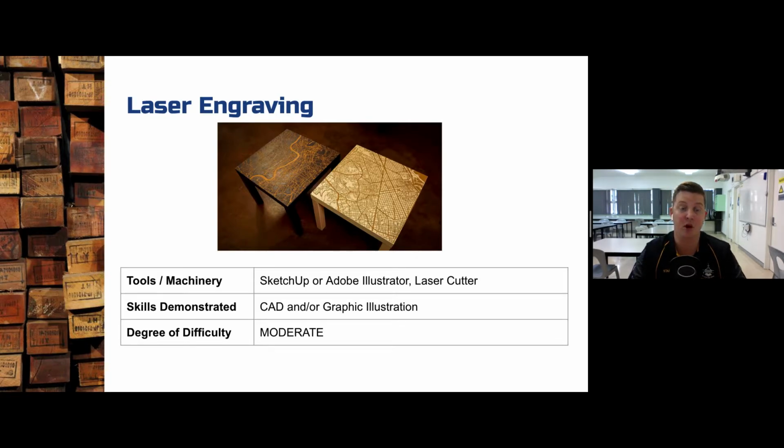Okay? On the opposite project you can see there, they've done the same sort of process, but it looks to me like they've had a stain in the timber, so they're working with a stained version of the light timber, so that when they've burnt through, it's actually brought that lighter colour back out and they have sanded the burn marks off. So instead of leaving the black behind, they've definitely sanded the burn marks off there. Okay. Typically, if you're laser engraving on a laser cutter, you're going to get black burning marks. So to get the lighter colours, once it's etched in, they're then going through and sanding that off to reveal the lighter colour.